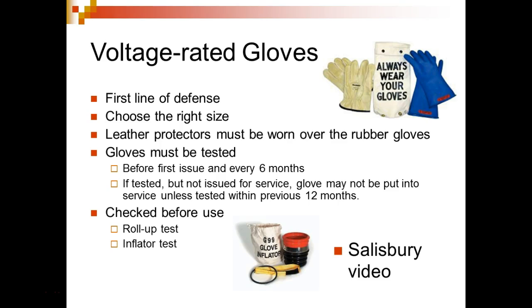What happens is that a motor has two currents. Anything at rest wants to do what? Stay at rest, and anything in motion wants to stay in motion. So a motor pulls a lot more current when it starts than when it runs. If you look at the nameplate, it says it's pulling 5 amps. Well, that's what we call the full load current. That's what the motor should draw if it's running at its rated horsepower. If it's running below its rated horsepower, it's going to draw less.